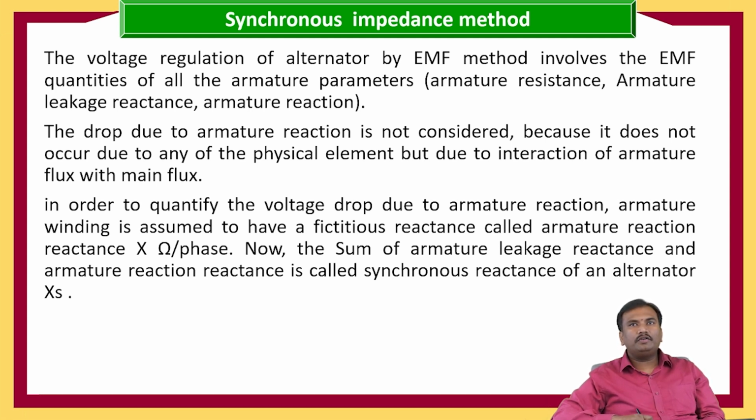The total drop due to armature reaction is not considered because the armature reaction value is less in the stator connected armature winding. It does not occur due to any physical element but due to the interaction of armature flux with main flux. Because this value is less, the voltage drop is very small, so we are neglecting it.